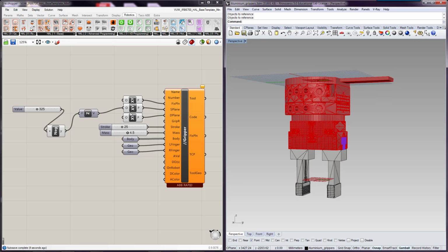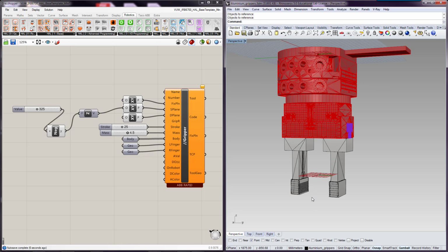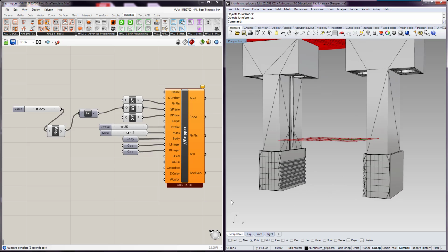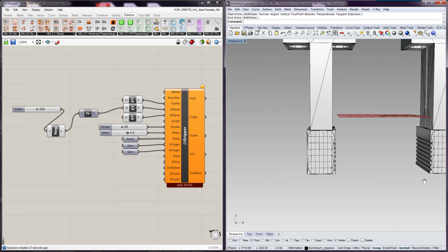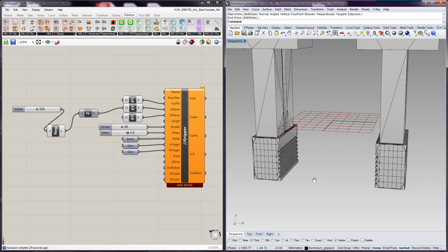That's one option. Another option which I like to do is to create a point. So if I came in here and started to draw a line, I'm going to have to snap to a vertex because this is mesh geometry at this point because I've meshed it out. All right, so let's try it again.